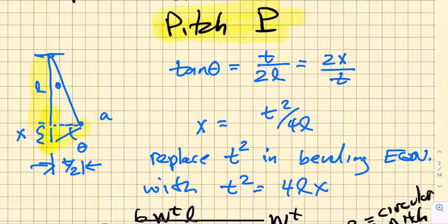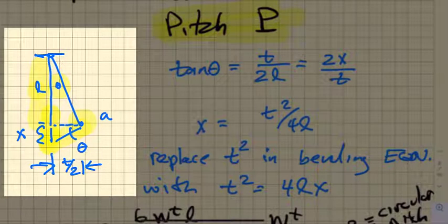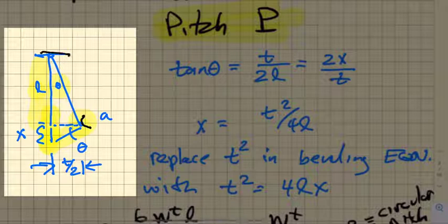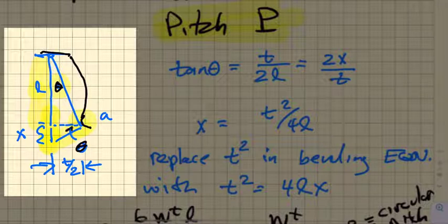at the bottom land. And we notice that this is going to generate angle theta between L and a line that goes from the center of the tooth and just goes tangent to the fillet radius. So the fillet radius is down here, the top land of the tooth is up here, and we have the involute profile that connects down to the base circle. And so this angle theta in here is equal to this angle theta, which is right in there. We know that this distance here is given as t over 2, and we come down a depth x.